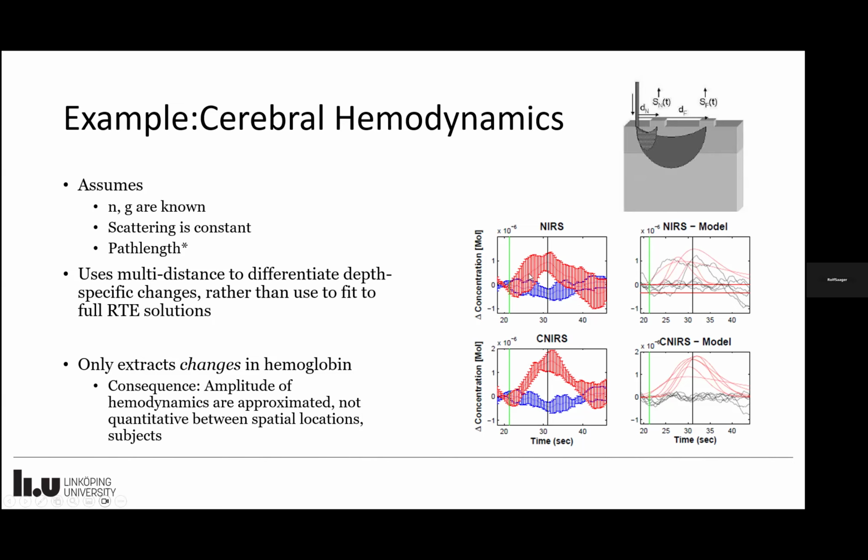Yeah. So with the NIRS, we just used the far source detector separation. So we just adopted the general technique everyone does, did the standard changes in oxy and deoxy with an assumed path length factor, and just process it that way. And then the corrected NIRS is where we did the scaled subtraction of the signals we detected here to try to clean up the signal.